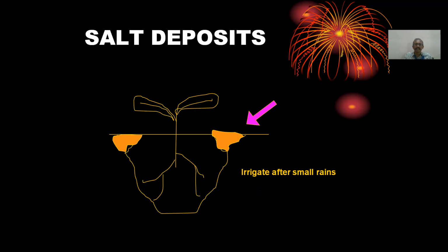With regard to salinity and drip irrigation, I would like to give some more explanation. In a saline land, when drip irrigation is operated, what happens? If you look here, this is the wetted front. When evaporation from the soil occurs, water along with the salt moves to the surface, and when it gets evaporated at the surface, only water goes. The salt gets deposited over the surface.